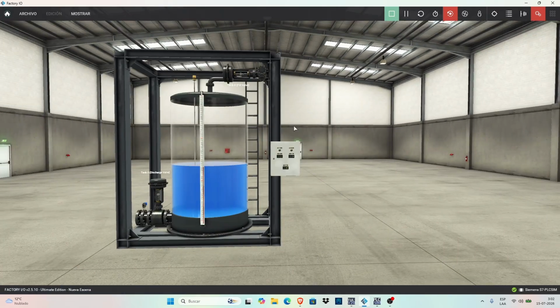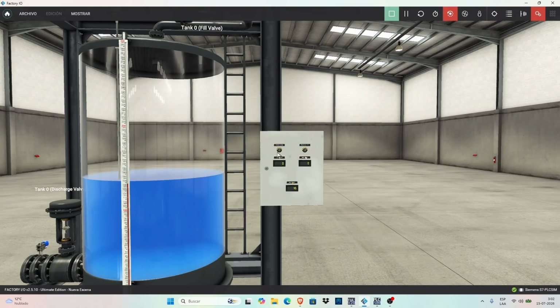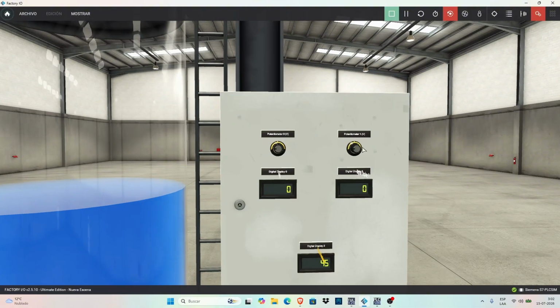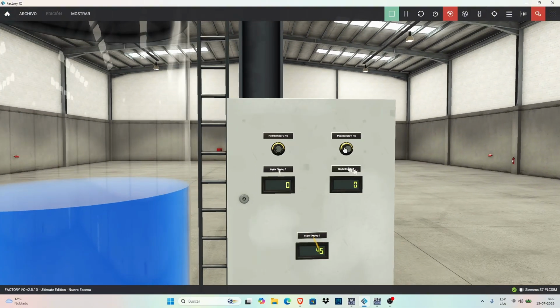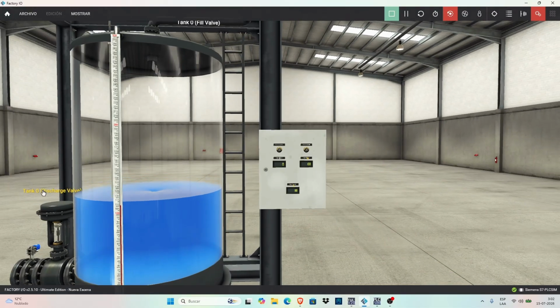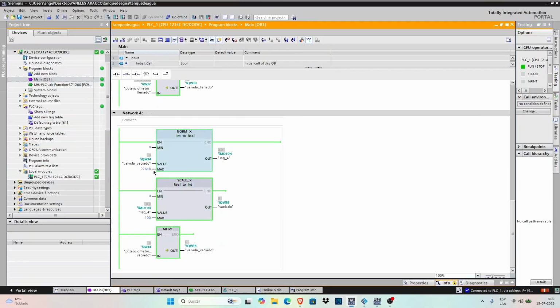We use the potentiometer to open the fill valve or also to open the drain valve. The tank has two valves, which is the filling valve, which is linked to the filling potentiometer, and the emptying one, which is with the emptying potentiometer. For example, if I open this one to 100, you see that it empties. And that is down here, the drain valve, you see that it is open to the maximum percent. And here it is in 1. 1 converts to 100% with scaling. This makes the emptying potentiometer whole. See?